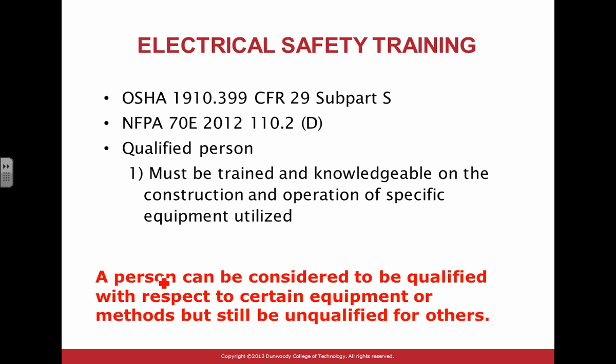That's good. Electrical safety training. Like I said, it is the law. You guys, that's why 3M put you in here. It's the law to do it. The law for us is OSHA, Minnesota OSHA. Right under these federal and state regulations, Subdivision S will tell you that you have to have electrical safety training, and NFPA 70E also tells you that you have to be a qualified person, and defines a qualified person for you. To work on any energized electrical system, you have to be a so-called qualified person.